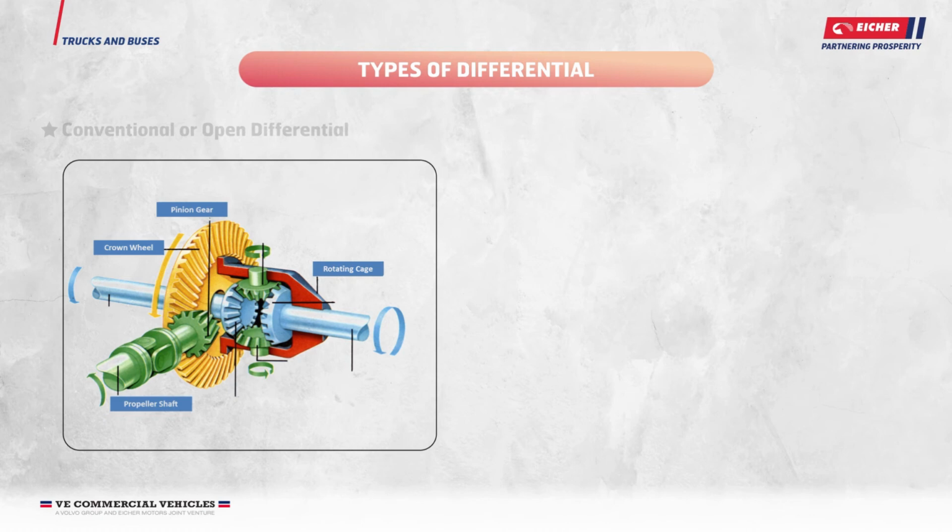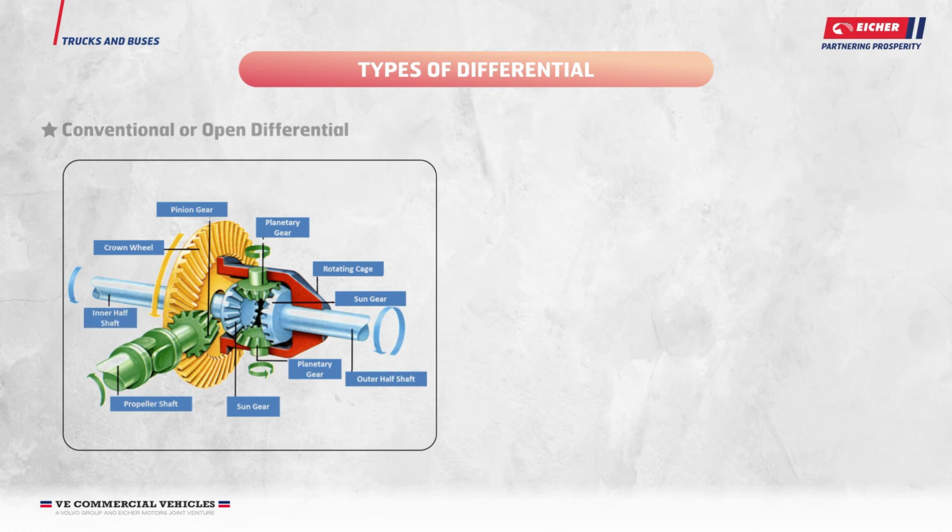The crown wheel gear is attached to the differential carrier or cage, which contains the sun and planet wheels or gears, which are a cluster of four opposed bevel gears in perpendicular planes. So, each bevel gear meshes with two neighbors and rotates counter to the third that it faces and does not mesh with. The two sun wheel gears are aligned on the same axis as the crown wheel gear and drive the axle half shafts connected to the vehicle's driven wheels. The other two planet gears are aligned on a perpendicular axis, which changes orientation with the ring gear's rotation.